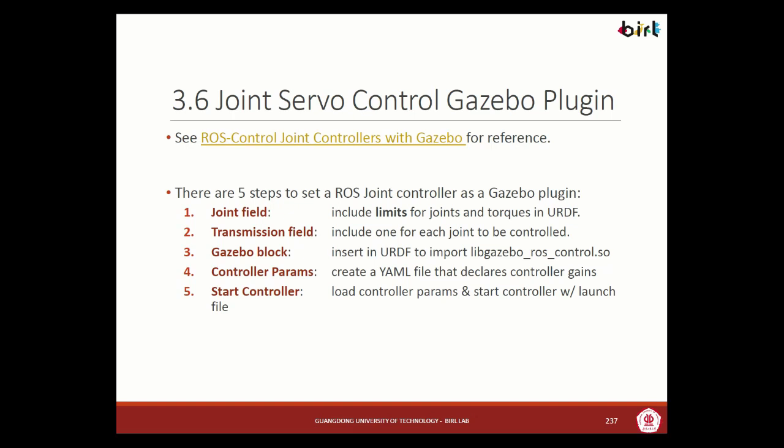Because we normally use gears or harmonic drives, and there's a transmission ratio from one to the other. Yeah, when the motor moves like this, maybe the arm moves like this. So we need to encode that transmission ratio. For these examples, we're going to use a value of 1. But again, your manufacturer would tell you what that number is.